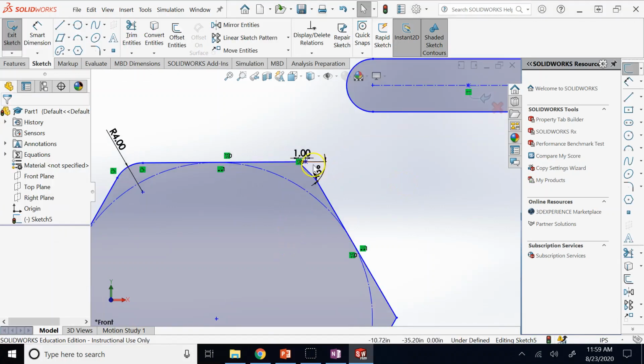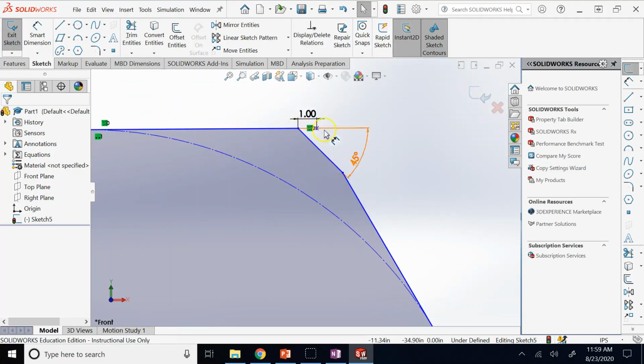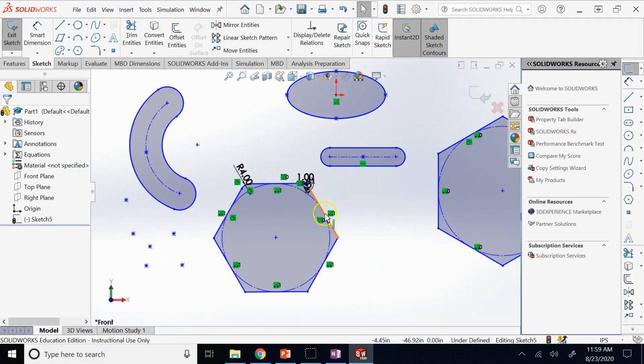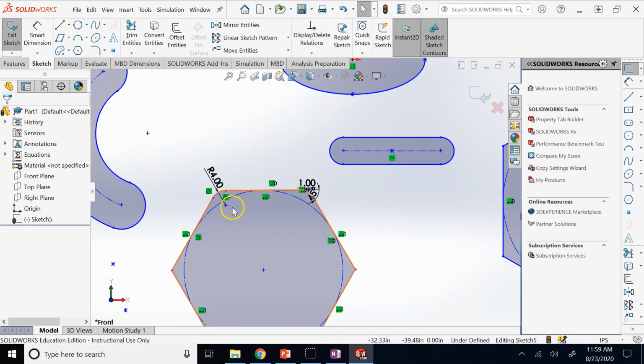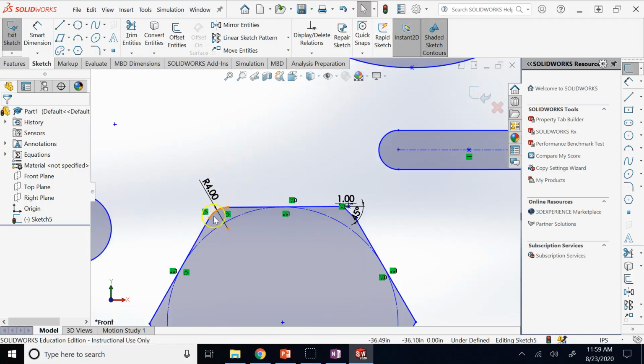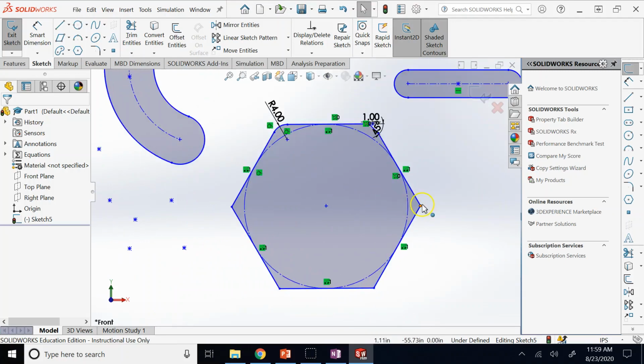Right, so you see that sharp corner that was here is now cut by a plane at an angle. That way of reducing sharp corners with a milder slope, we call a chamfer. That is used at the bottom of bolts, if you have seen, but fillet is mostly used to get rid of sharp corners. Why do we get rid of sharp corners in many applications? First of all, sharp corners and sharp edges, as the name says, are sharp, so they can cut the hand of the operator. The other thing is if they are internal edges, okay?